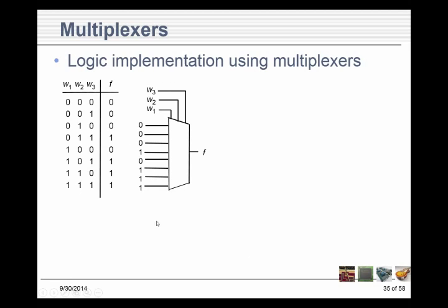And it is so much easier to develop circuits with a multiplexer than it is to do it with all the other gates. For example, I don't even know what gates this is. I don't know what the equation is here yet. I know what the summation expression is. It's 3, 5, 6, 7. That wasn't too hard. I could put that in a K-map. That wouldn't be too hard. Well, I mean, we could put it in the K-map real quick.